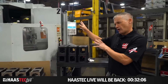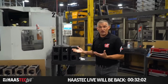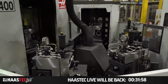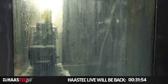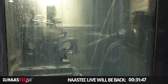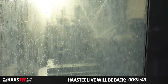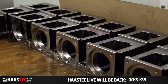All of these cells mostly concentrate on 1 or 2 parts or a few parts where we're doing very high volumes. But you can see, when you attach a pallet pool like this to one of these HMCs, you've got a lot of fixture positions. And the idea is, with the pallet pool loading and the pallet changer loading those pallets in and out of the machine continuously, your spindle on time is maximized. You can see right here, we're making motor housings for our machines. Just one example of all the different parts we make on this line here.